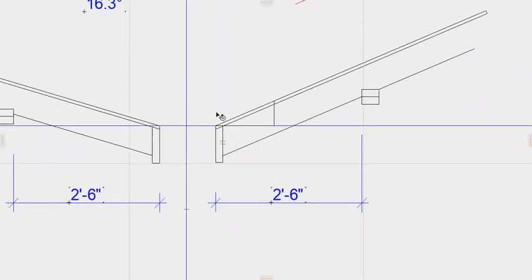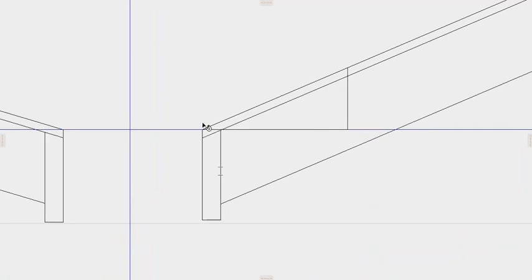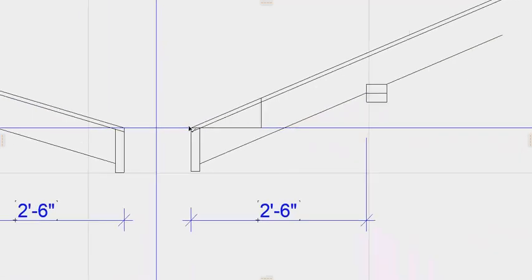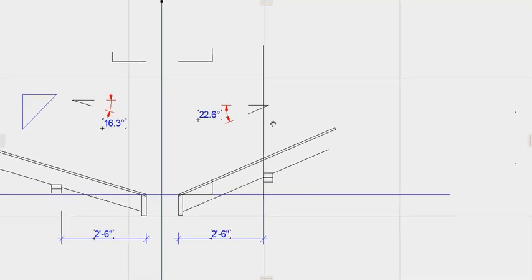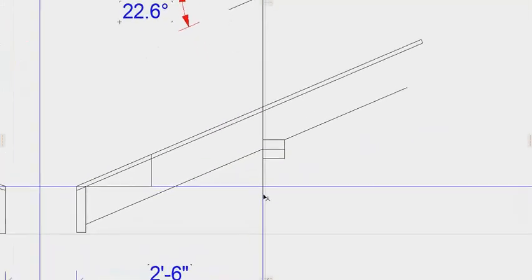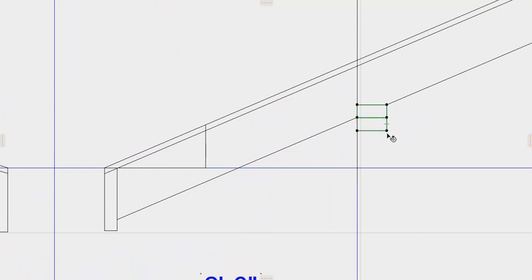And what you can do then is you can make your level cut on the end of your rafter. So wherever your slope meets that line, you want to measure over whatever your overhang is. In my case, it was 30 inches. So I'm going to go from this line that's made right there, and I'm going to offset, measure over an additional 30 inches that way, and snap a line right there. If you snap that line and carry it through, and it's nice and parallel to your line here, so you can always double check with your tape, that gives you the edge of your top plate.